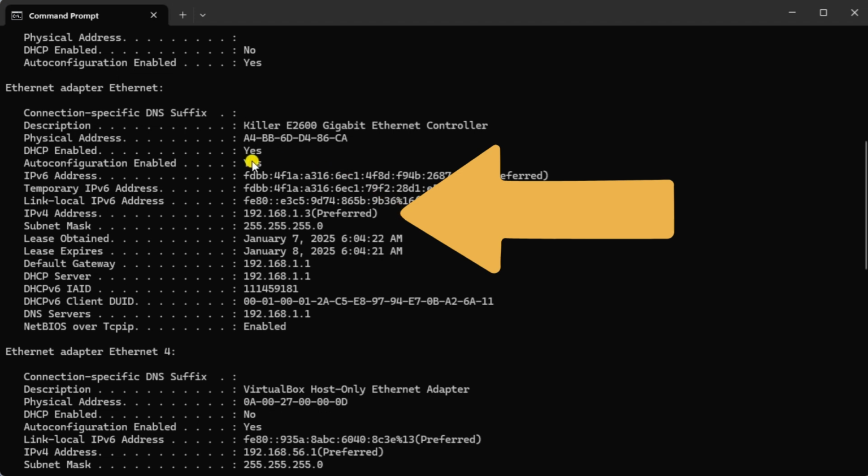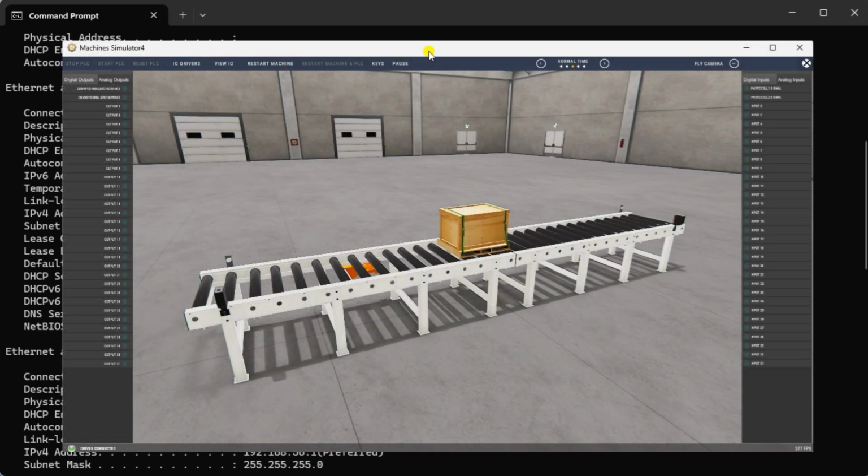The realistic simulation environment is now on the network as a Modbus TCP Ethernet server. We can now test or create multiple control programs for our selected simulation scene. Integrating with multiple PLCs, or programmable logic controllers, including the Click PLC, is easy, as the PLC now acts as the Modbus client. This cost-effective training tool reduces the costs and risks of working on physical machines.